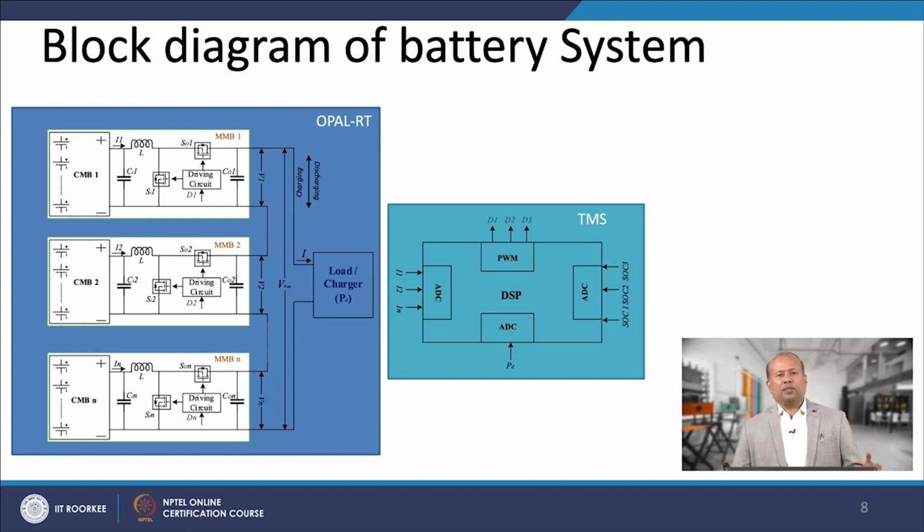The system consists of 3 modules and a boost buck converter each, to step up or step down the battery voltages as per the requirement. Such a mechanism is called energy sharing because each module can be controlled individually, which resembles the sharing of the power demand accordingly.